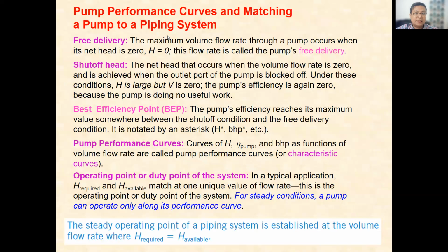Okay, you can see this one is how we calculate the power supplied or required in that design. So after we calculate with the Bernoulli, and we involve the head loss also because of the piping system and all instruments inside the piping, then after that we compare how much power is needed to supply the system.